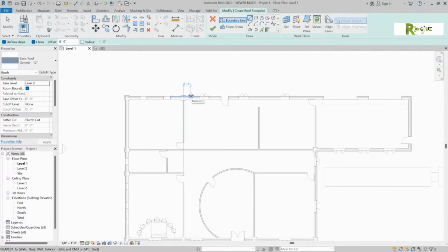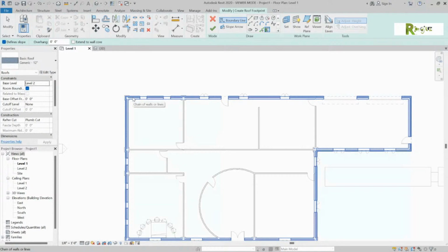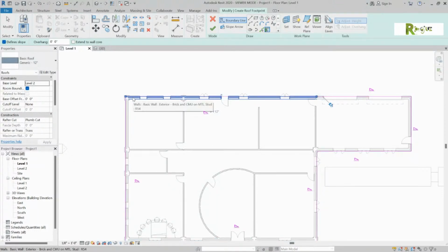And in the next one where we did our draw arc, there's a special one that says pick walls. It's the green one right below that. Perfect. Pick that. Now go over that wall and don't pick till I say. See, you would have had to pick all the walls around there. But what if you're over one wall and you hit tab? Look at that. It just traced all the way around all the walls. Now you pick, and it just drew all of those lines in.